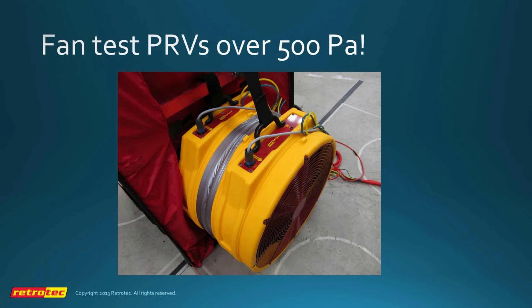We've got one running clockwise and one running counterclockwise, and they will test PRVs well over 500 pascals, but at high flow rates at 5,000 CFM. If you need something like that, we can provide it for you. But we recommend that you take your PRVs, mount them into a box, and depressurize the box so you're not blowing air at the PRV. Turn the PRV around to test it in the other direction to make sure that they open at the prescribed pressure. You can also measure the free vent area of the PRV using your door fan using that method.